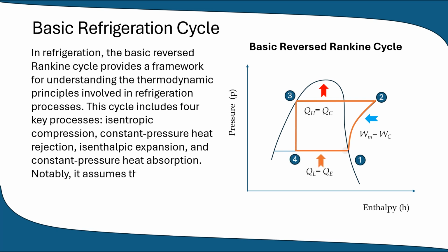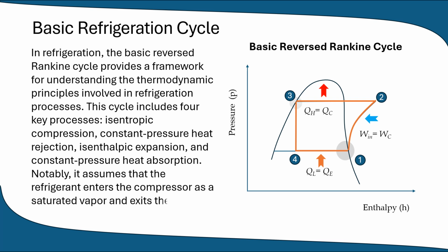Notably, it assumes that the refrigerant enters the compressor as a saturated vapor and exits the condenser as a saturated liquid. You can watch the video Introduction to Refrigeration to gain a deeper understanding of the thermodynamics of the refrigeration process. The link is provided in the description. In this video, we'll examine the modifications made to the basic reversed Rankine cycle to enhance its performance. This basic reversed Rankine cycle is also known as the simple saturation cycle.